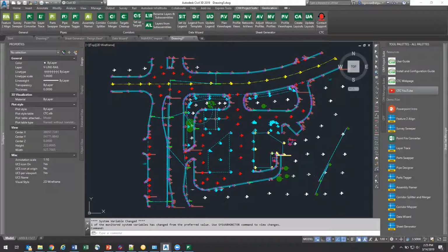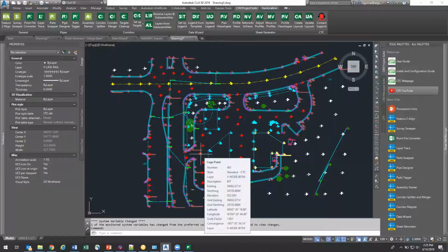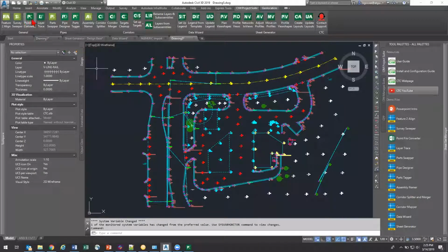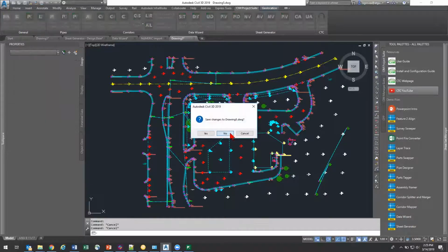And this is how we're going to go ahead. We're going to set up known survey code set A. I know how that's going to turn into known survey code set B. I don't have to find and replace inside all of those files. Point file converter is just going to do that for us. So that is that tool.